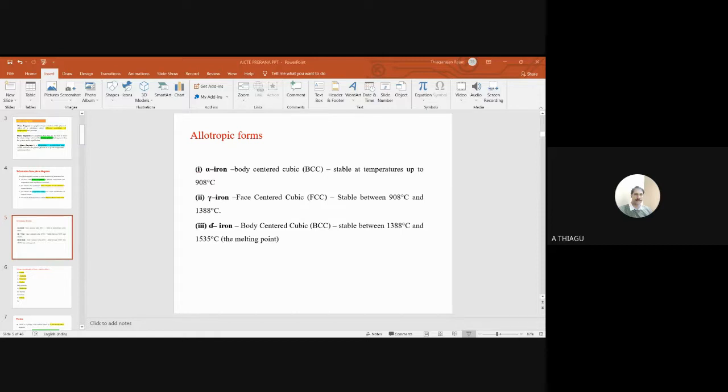So you can look at the thing. So this is the formation I already suggested to you. Where we find some river-like appearance, all comes under eutectoid. So this is nothing but the area, and the remainder all comes under alpha. The blue color will represent it. So alpha and cementite is called pearlite. So once you observe this kind of image, we can confirm it is a pearlite structure.